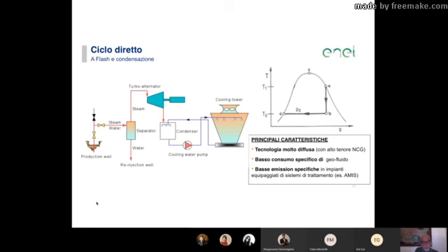you drop down all the solids, you leave a solid residue directly in your geothermal system, and these solids do not clog up the wells. If you would produce the flash inside the well, then all the residue will clog up the well immediately. And this is why you would like to produce the flash right into the geothermal system.